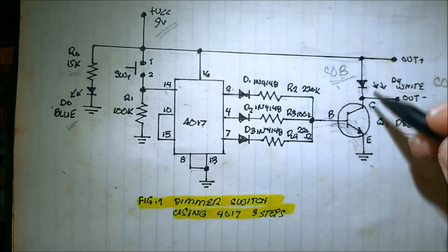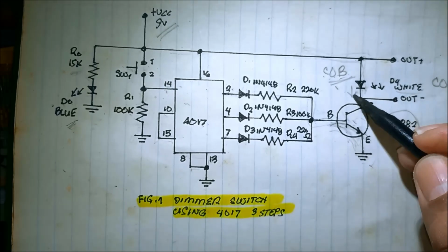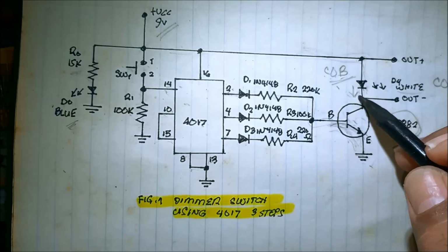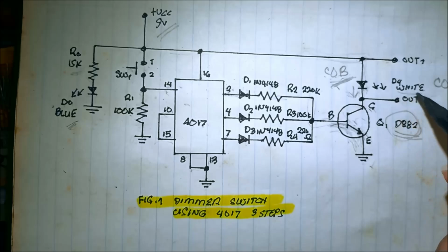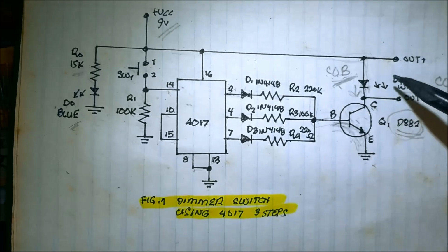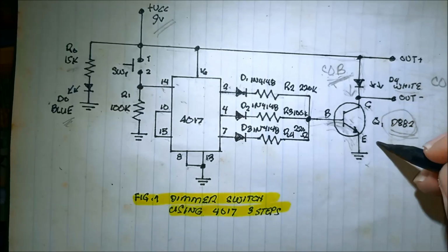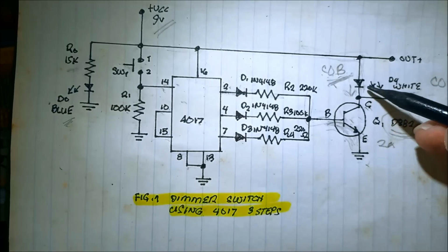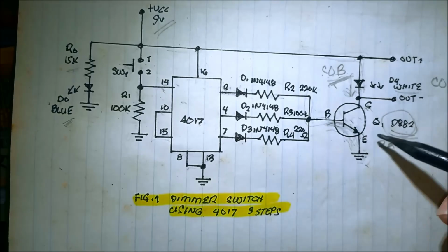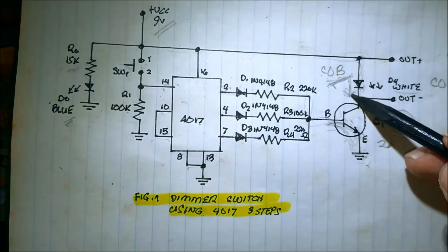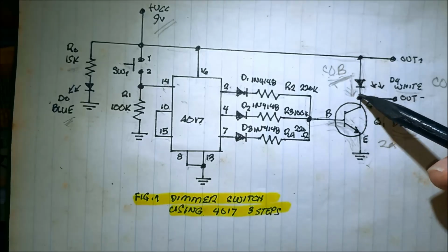So we need the high power transistor because the current to the collector is very high because of this high powered white COB LED. This transistor is capable of handling up to 2 amperes of collector current that flows to the collector, to the emitter, then to the ground. So it acts as a driver to the COB chip on board LED.